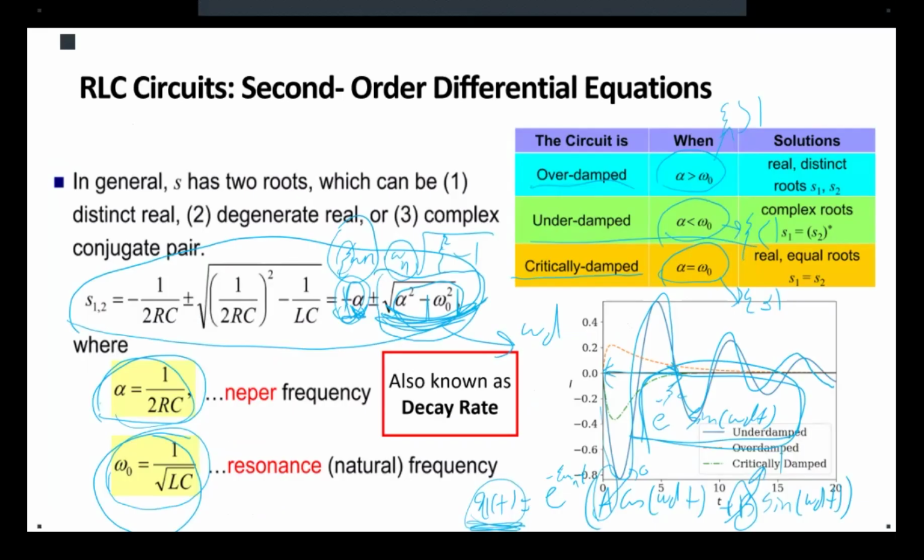The decay rate is found from the time it takes the waveform to go from the peak value to 63% of the peak value. I already put that hint in the lab assignment. And the peak value is easy to measure. It's just there.